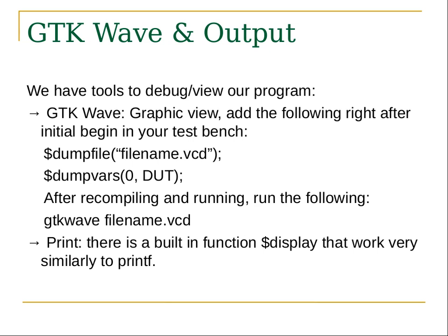Graphic view. Anyway, you have to specify where you want the dump file to be when you run your simulation, and then you tell it what variables you wish to dump. And then you use GTKWave on the file that contains all your dumps.